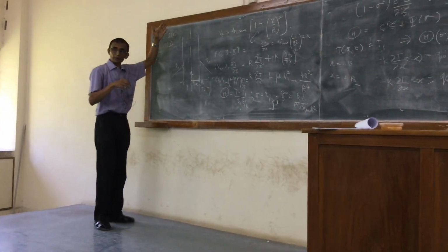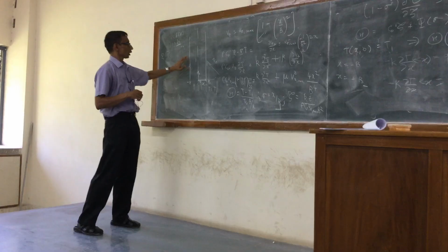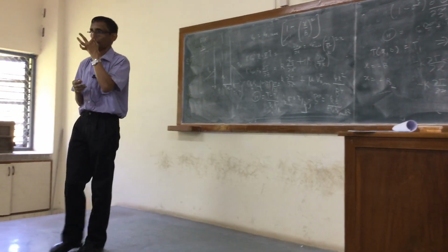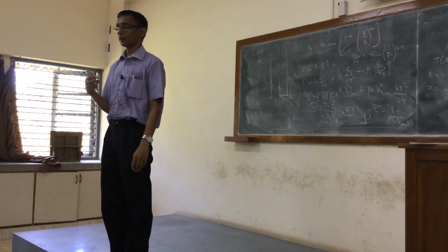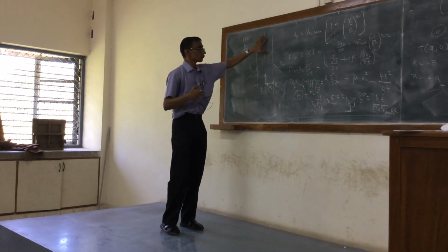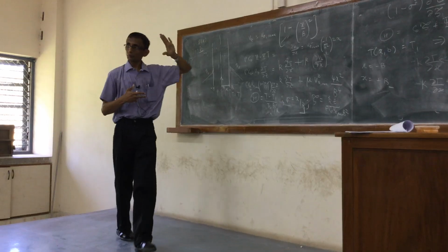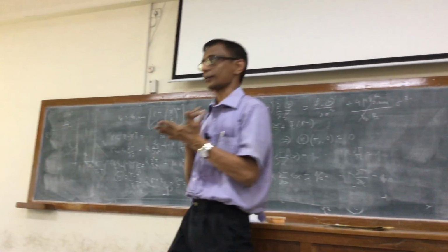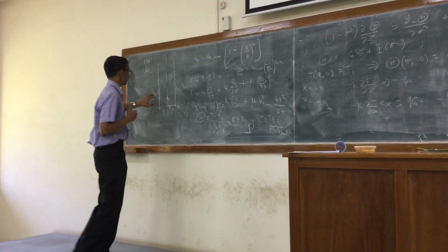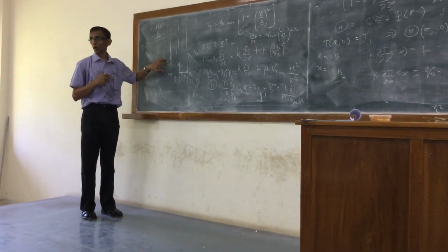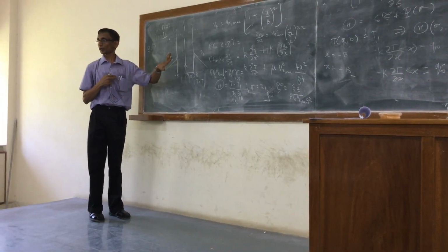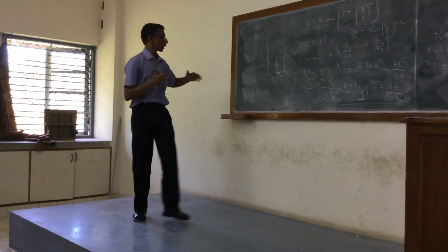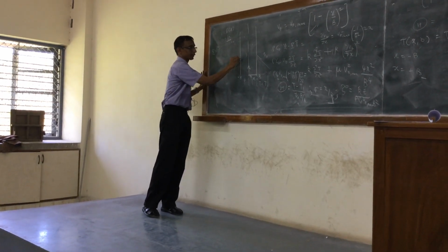What it really says, when you have a boundary like this, because outside the cylinder you are providing heat by whatever means. Inside, not the cylinder, inside there's a fluid, right? The principle which will lead to an unambiguous equation is that I find it convenient to assign a certain direction to Q naught. You can assume either it is heated or it is cooled. When it is heated, as I said, I put an arrow here, that means Q naught will be greater than 0.